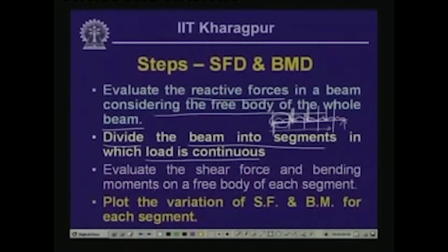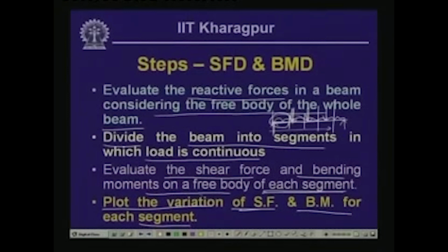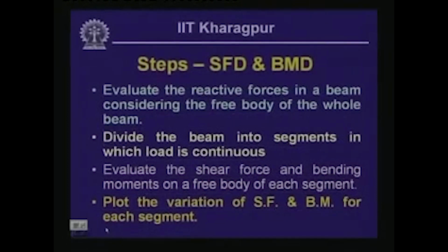So, this is what is mentioned over here: evaluate the shear force and bending moment on the free body of each segment, and plot the variation of shear force and bending moment for each of such segments. Once you do that, you will get the shear force diagram and the bending moment diagram of that particular beam. So, these are the steps one has to go through to draw the shear force and bending moment diagram.